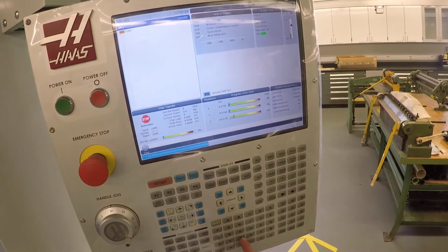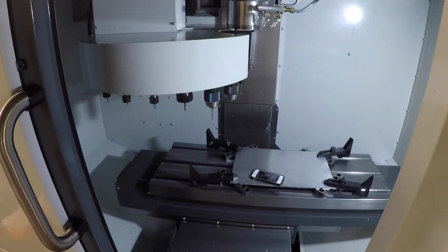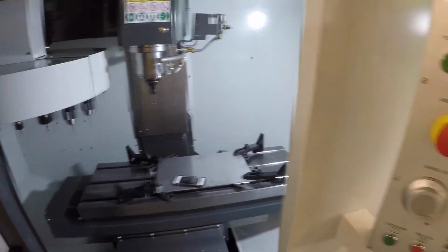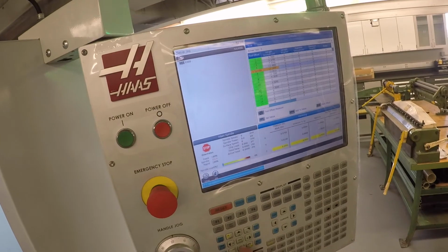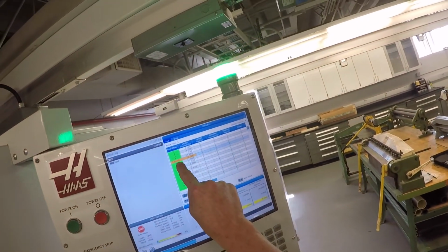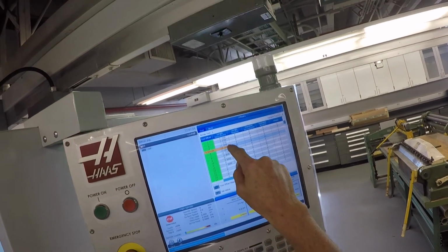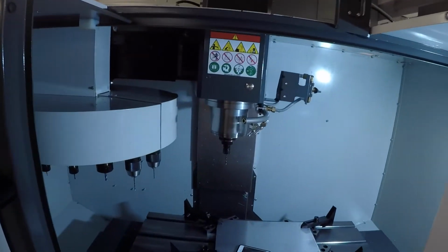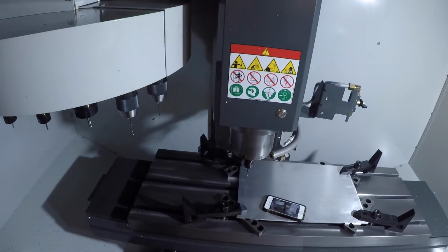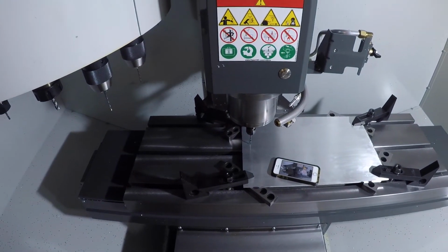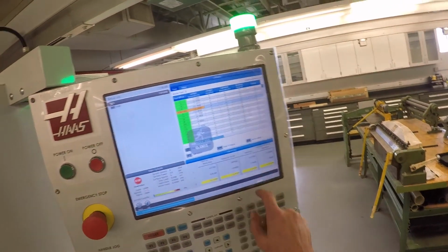And next tool, so tool 5. Okay, and then we'll just Z down. Oh, handle jog. So T5, spindle, right? Tool offset, 5 is in the spindle, and it's saying the last tool, whatever that last tool was in there, that was its offset. So we come down here. Real slow. Thousandths place, so it's highlighted, right?